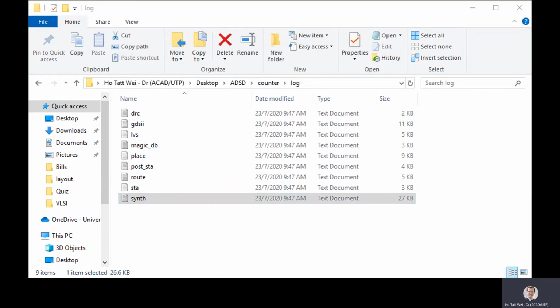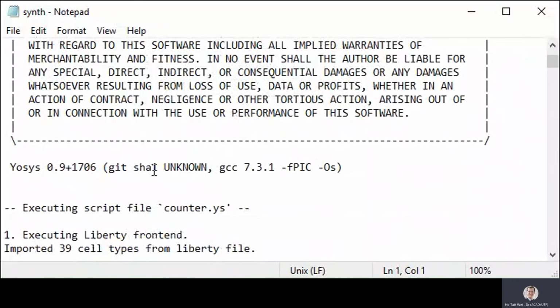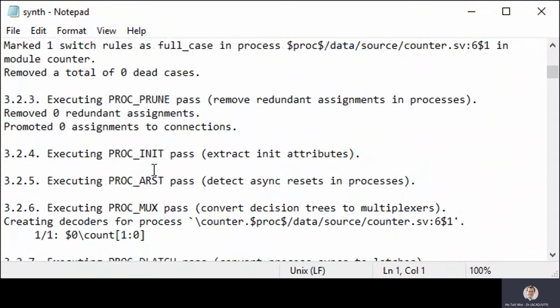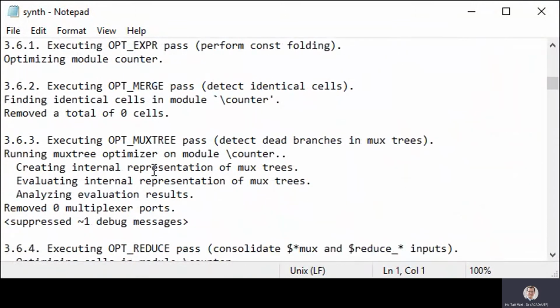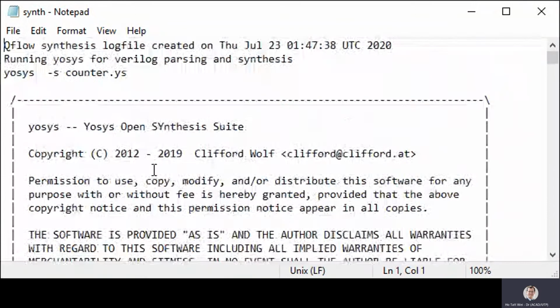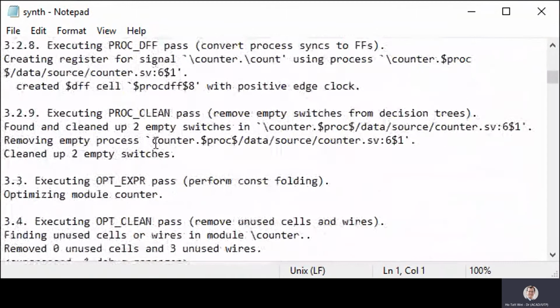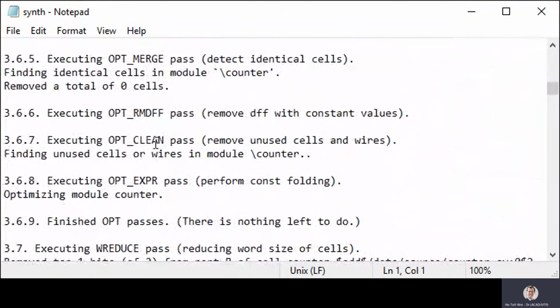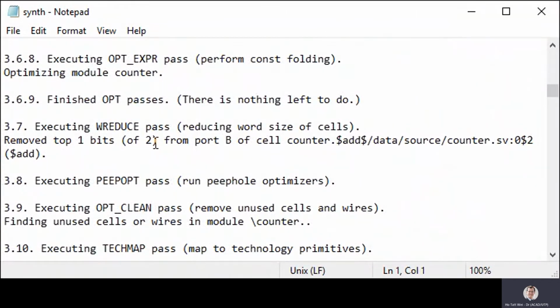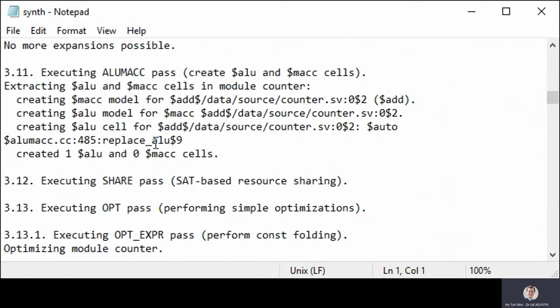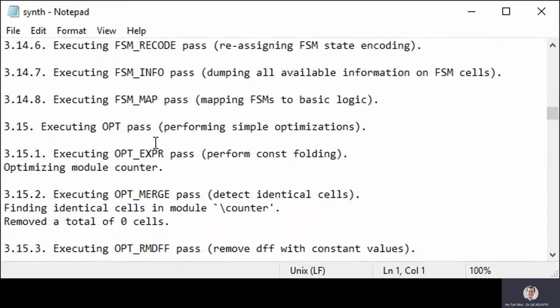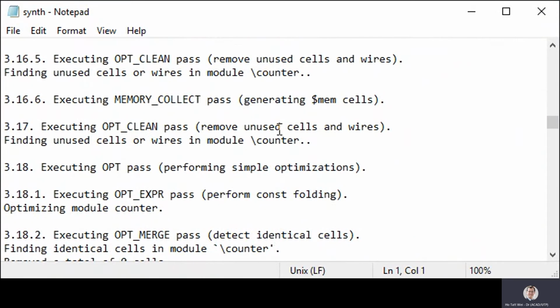So if you open the file, you will be able to see the qflow log reporting all stages of the synthesis test step, and this is of course using the Yosys software, and you can check whether there have been any errors in any of the intermediate tasks and any of the reports on success or failure of the task, and then appropriately debug it if it's in error.